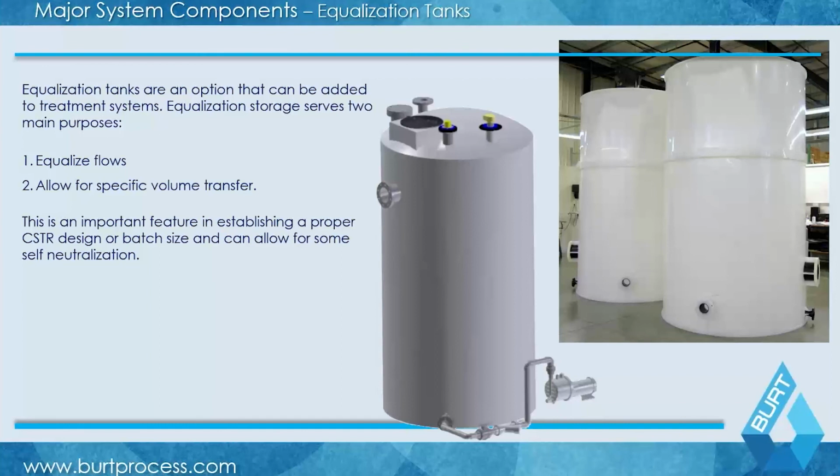A little bit separate from the pH neutralization system, but also oftentimes working in concert with them, is equalization tanks. An equalization tank is a tank located upstream of your pH system that really serves two main purposes. One, it allows you to equalize the flow coming into your system. And two, it allows for specific volume transfer should you be involved in more of a batch style system.